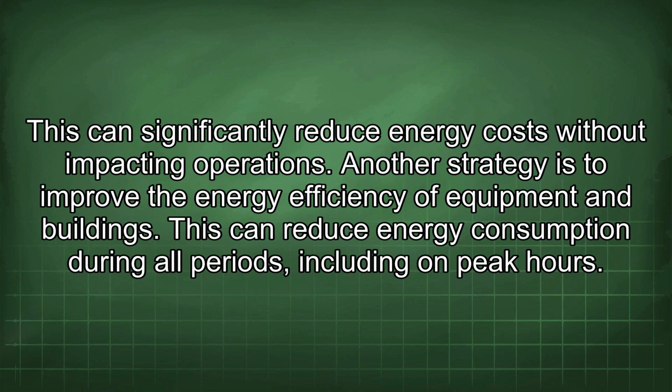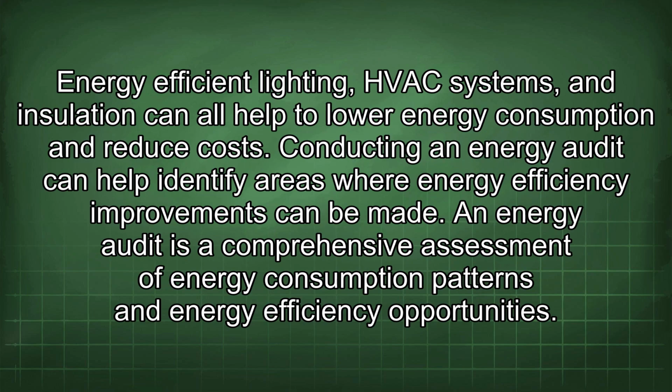Another strategy is to improve the energy efficiency of equipment and buildings. This can reduce energy consumption during all periods, including on-peak hours. Energy-efficient lighting, HVAC systems, and insulation can all help to lower energy consumption and reduce costs. Conducting an energy audit can help identify areas where energy efficiency improvements can be made.